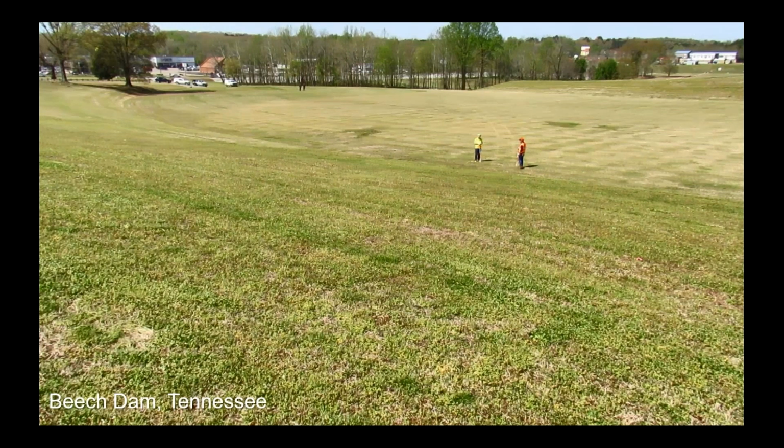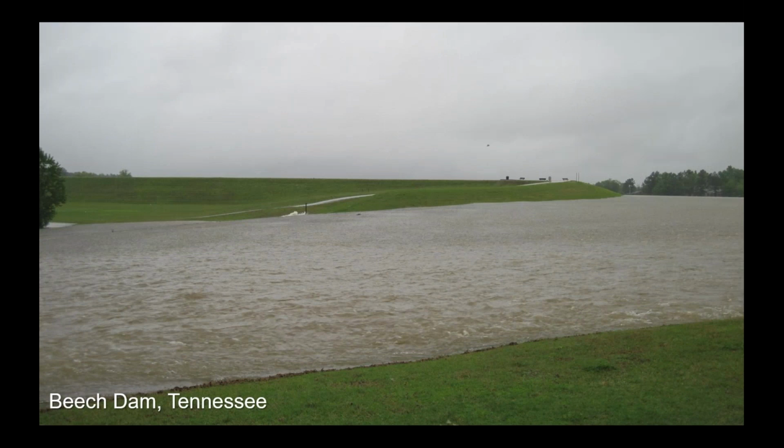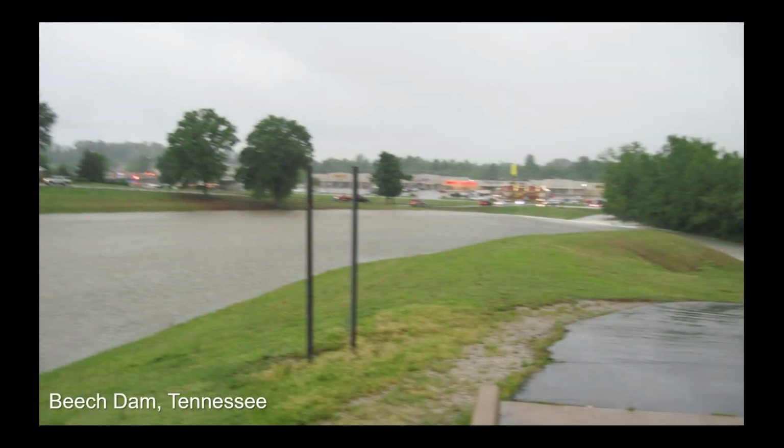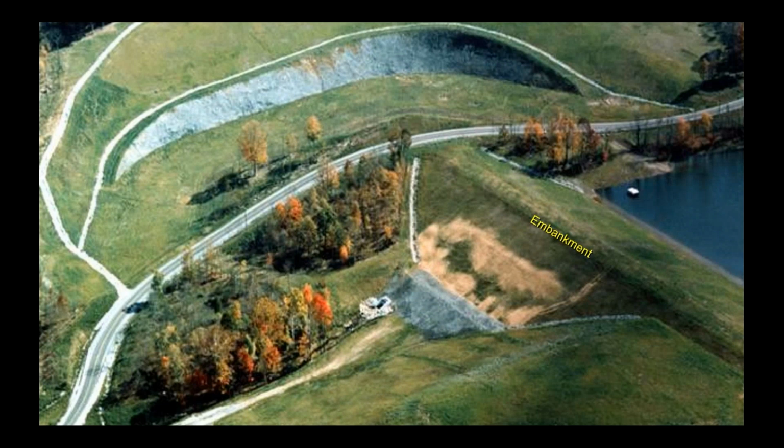What would this look like during a flood event greater than the 100-year? Well, this particular spillway did flow, and we happen to have some really good photos of what that would look like. So this is a very well-maintained spillway. You can tell that the grass is well-maintained, it's mowed, and when this spillway was activated, you can see how well it performed. The water is nice and uniform, and at this point, the flow is moving supercritical, so it's moving pretty fast, and the spillway is performing very well, just as it was intended to. So that's an event that exceeded the 100-year flood event.